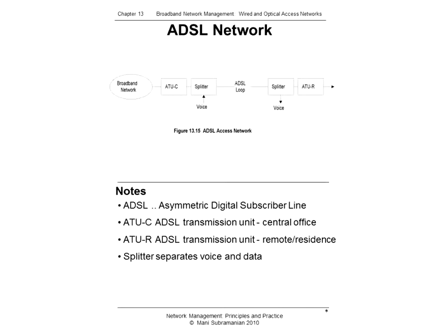So when we have discussed them one by one, we have seen that HFC basically carries information from the head end to the customer premises by using optical fiber and coaxial cable. That's why its name is hybrid fiber coaxial cable network. And there are cable modems at the customer site and a cable modem termination system. So transmission is two-way in most of the implementations.